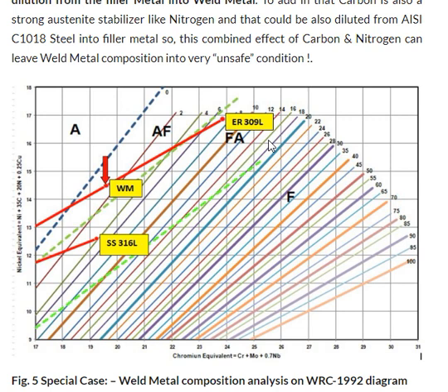The role of the ferrite content is very important with respect to dissimilar metal joints in stainless steel. When we are joining stainless steel with stainless steel with a matching consumable, say for SS304 we use ER308, or for joining the same base metal SS316L with ER316L filler metal, there is no question, because the chemistry of the filler metal is designed such that we can comfortably get the ferrite number between 5 to 8.